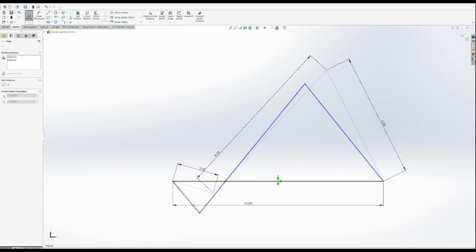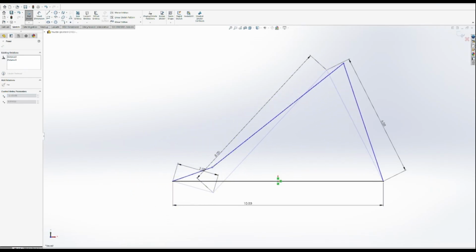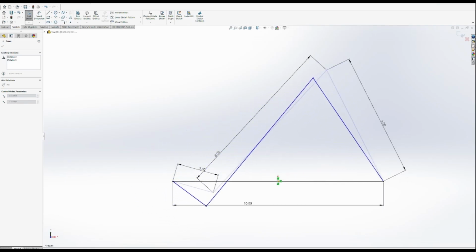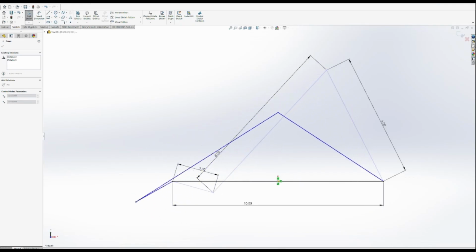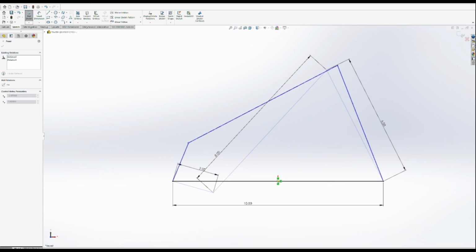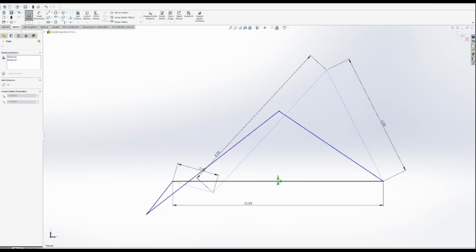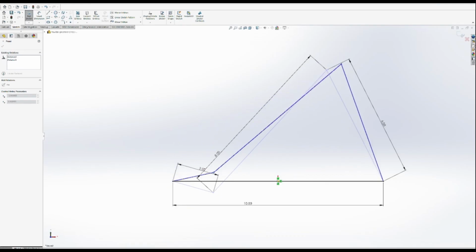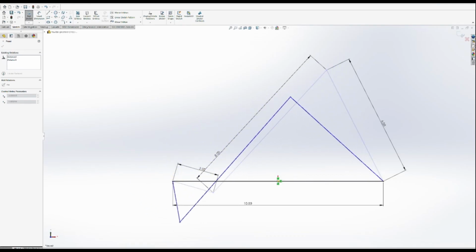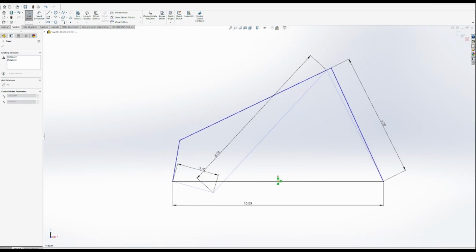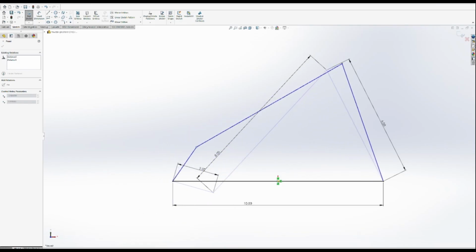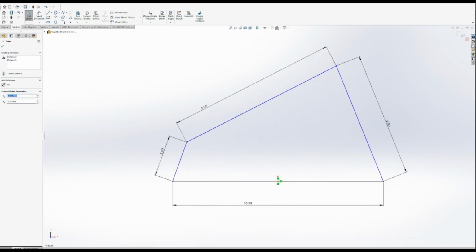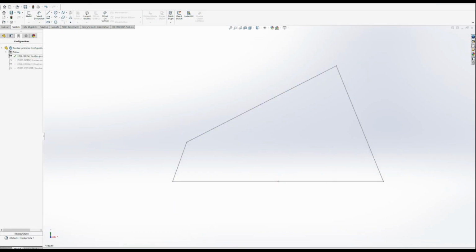And you can imagine that associated with this input link is maybe a servo motor or a stepper motor or a brushless DC motor or something such that you could crank this input link all the way around and it can make a full rotation relative to the other links because it's a Grashof linkage just like this. And this is how the linkage will move. And we would call this a crank rocker linkage, because this output link is rocking and we are cranking the input link such that it is making a full rotation relative to the other links. So essentially over its entire motion profile, the linkage will essentially just do this, and it can also go in reverse, okay?